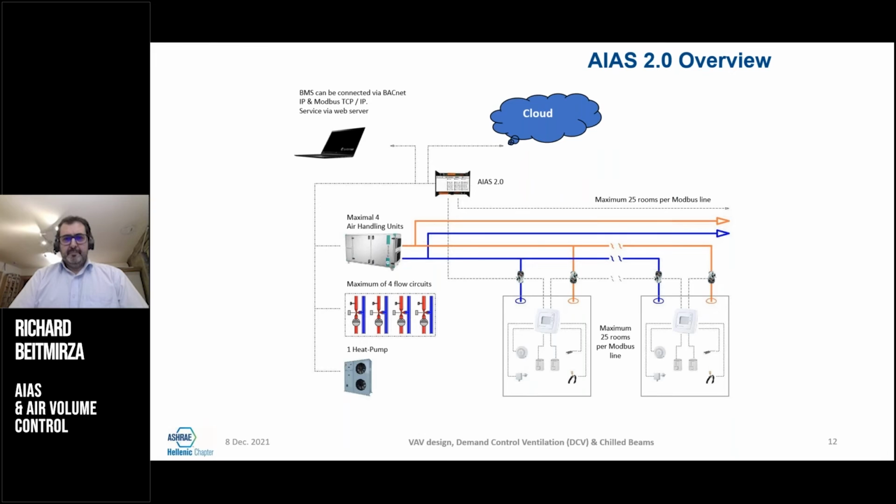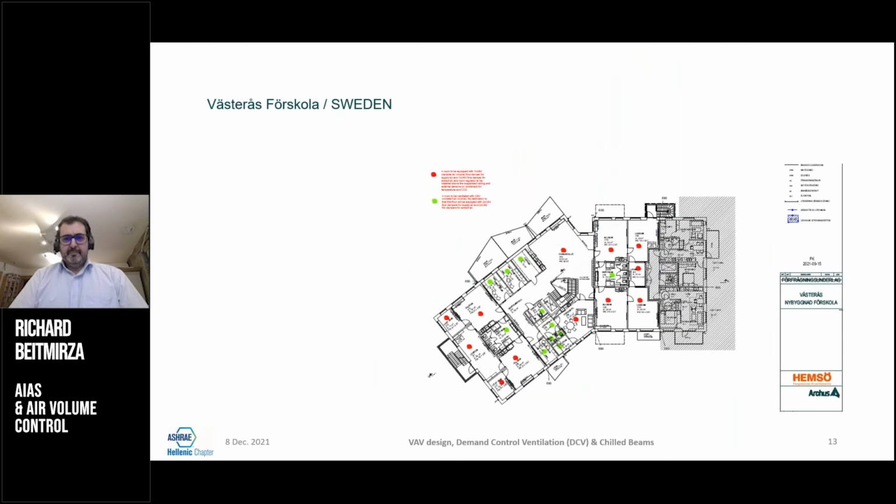In a small system, you can even control the average use of your heat pump. So it's not working based on outdoor temperature, but is working based on demand and the use, and it will continuously retake the average. And it can also control a number of series of water valves that is required for heating or other uses. So this demand control can be taken to a really high level if it's needed.